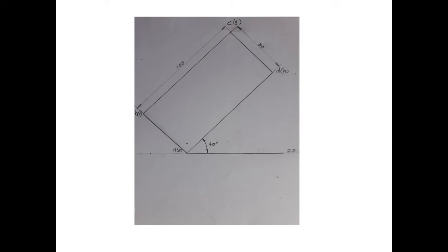It is given that the object is a rectangular prism of 100 by 50 by 40 mm, and it is lying on the ground on its rectangular larger face, that is the 50 by 100 mm face. So you draw a line to show the picture plane. This is the picture plane. Then in the top view you can see the 100 by 50 mm face because it is lying on that face. Also it is given that one shorter edge, the 40 mm edge, is touching the picture plane.